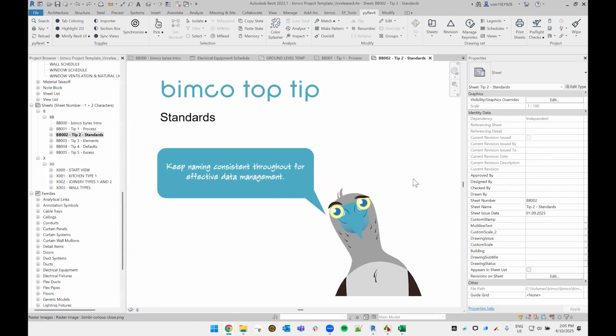Lastly, with standards, complete the change in one sitting. If you're undergoing a project template upgrade where it requires a lot of repetitive work across many different elements, say view templates, don't start it knowing that you're not going to finish it or you'll be in a mad rush. Start it when you've got the time and you know you can finish it. It's very difficult to come back and continue and remember where you left off.